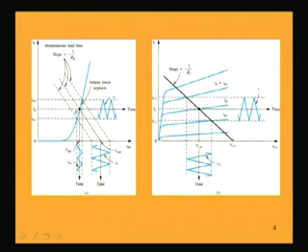The DC base to emitter voltage is capital V capital BE, and the current flowing in the base is the DC current capital I capital B. So, for that particular voltage, this is the current IB. So, the Q point in the input characteristic defines the DC voltage between base and emitter and the base current IB.